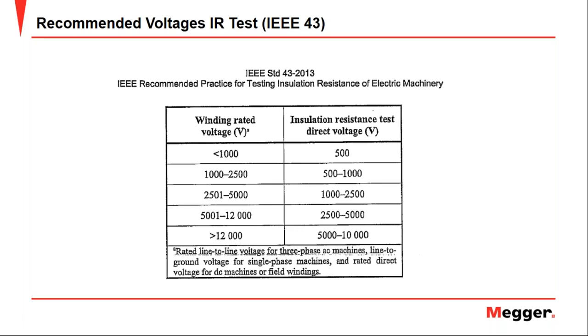The next one is a little bit longer: is it standard that when the system phase sequence is 1, 2, 3, and phase 1 is connected to lead T1, phase 2 to lead T2, and phase 3 to lead T3, the motor will rotate in the clockwise direction when facing the shaft, as you have described?